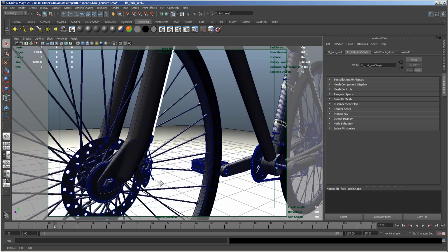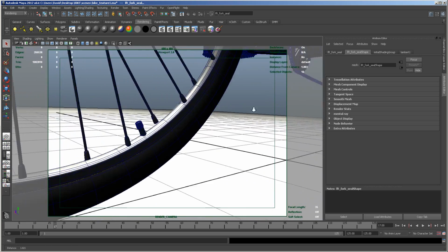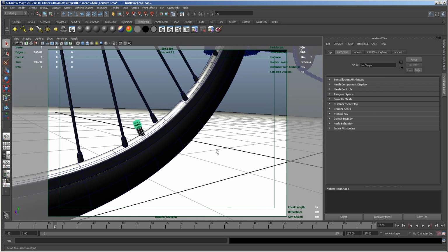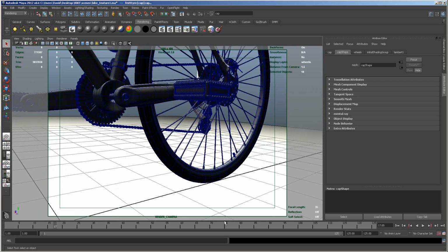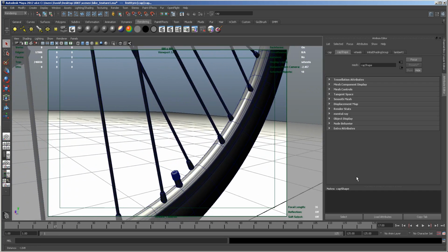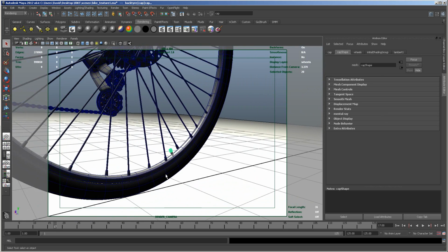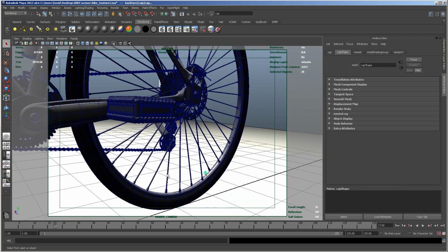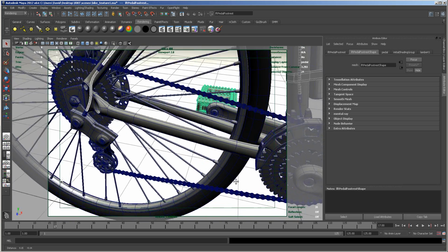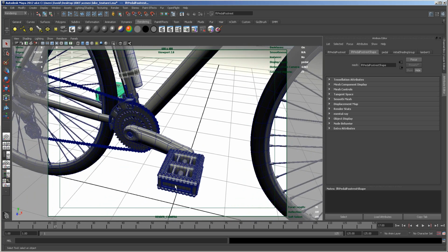And I think I'll even go down and put the same on my inner tube and cap there as well. If you can use the same material and then you render at the end and see if it doesn't look right, then you might have to do a separate material for it, but if you can get away with it, then use the same. And I'll even take my pedals, which are going to be a plastic as well,